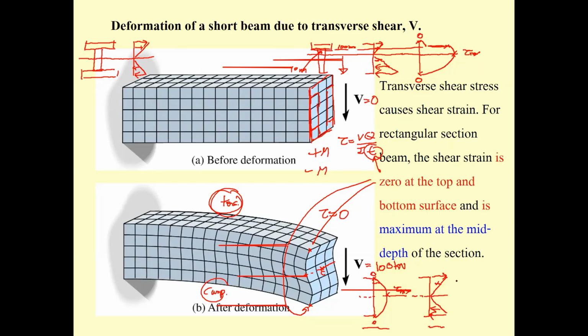This one and this one is the same, right? Yes, it's the same, because both of them are double symmetry. But the shear is different. The shear on the top is 0. Okay? The shear on the top is 0. On the bottom is 0. But the width here is 100. The width here, for example, is 10.